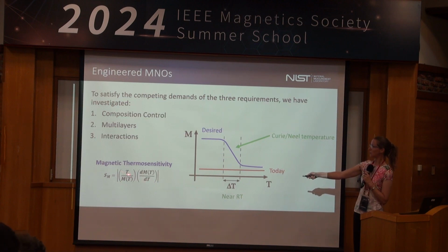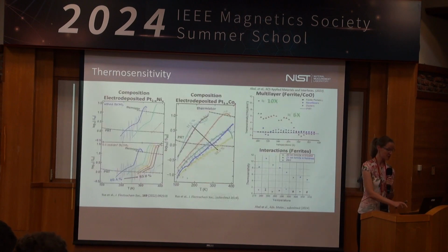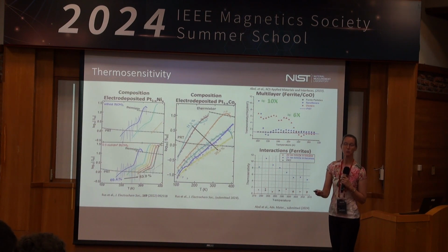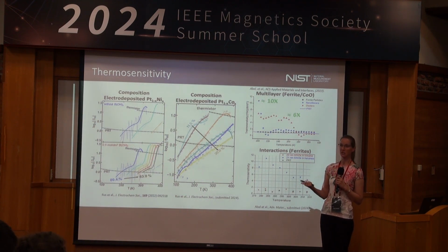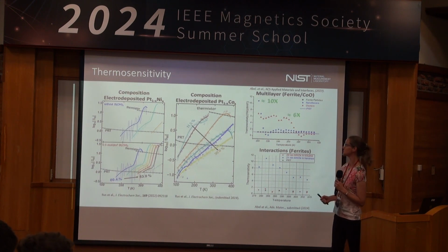But it is normalized by temperature over the magnetization. And the reason you do that is so that you can compare it with literally the standard. And the standard in this case is the standard platinum resistance thermometer, which is actually what is used in part to make this traceable to the SI, specifically to the International Temperature Scale of 1990. I'm happy to talk about that for people who are really interested in standards.